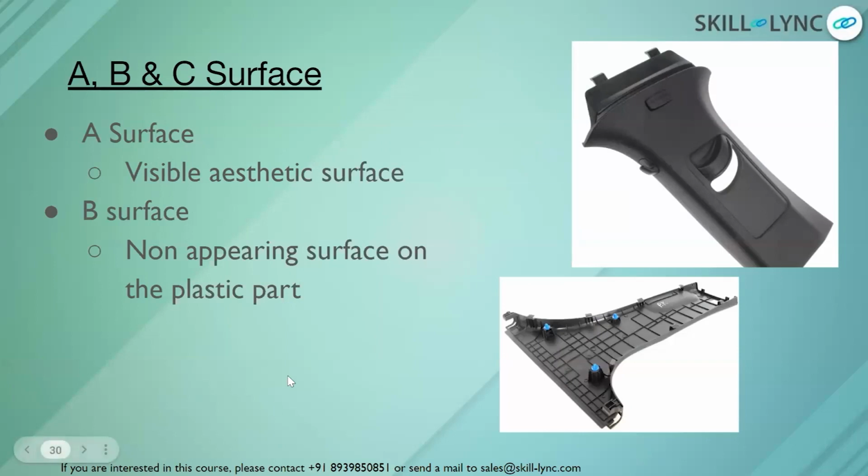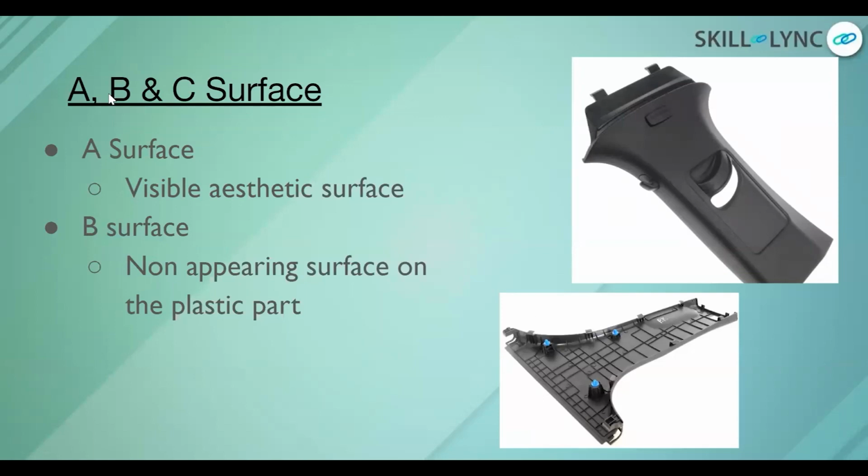So in the general case, plastic components will have a thickness. There is a standard parameter for the thickness which you are going to provide to your plastic components. So plastic components are going to have a thickness of around 2.5 to 3 mm. Okay, so that is the general thickness which we provide for plastic components.